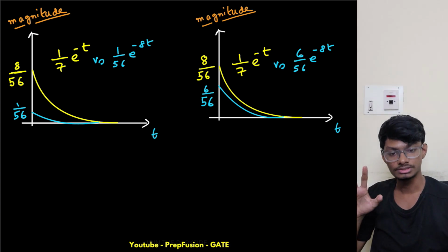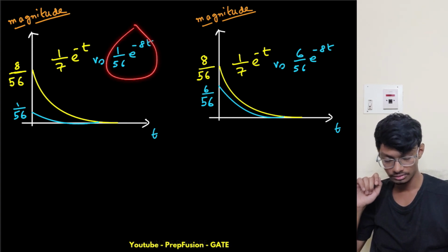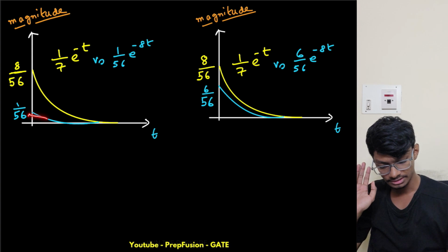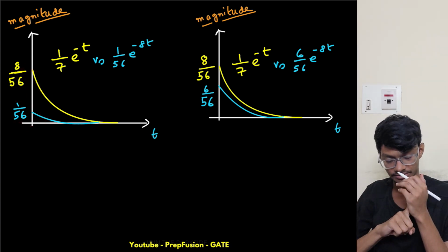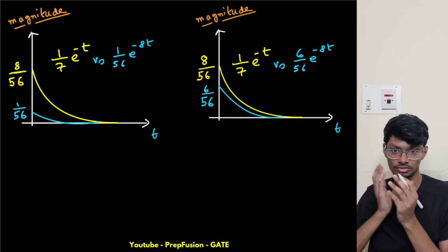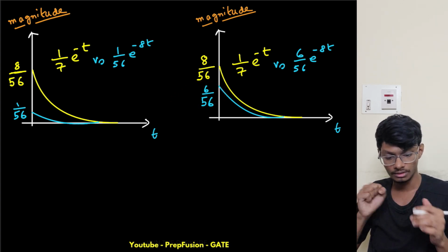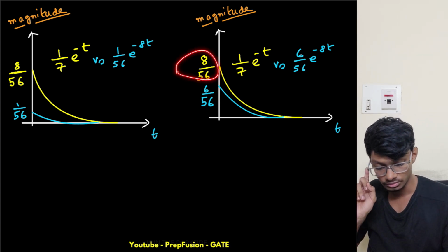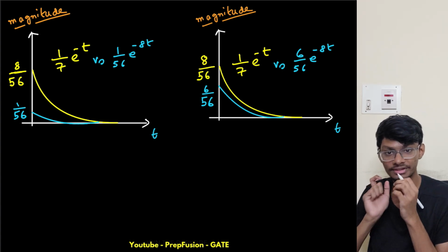The difference that you see is that this was the pole that we used to ignore in dominant pole approximation. So here I can see this is minimally affecting my dynamic response, right, not affecting my dynamic response. But when I introduce a 0 at s equals to minus 2, this is getting more dominant. Okay, this is getting more closer to my dominant pole. So my dominant pole has reduced its dominance.